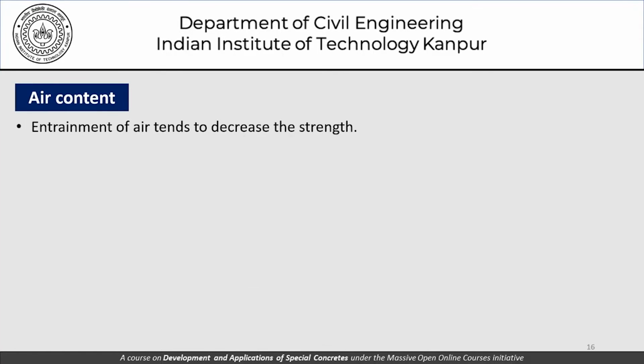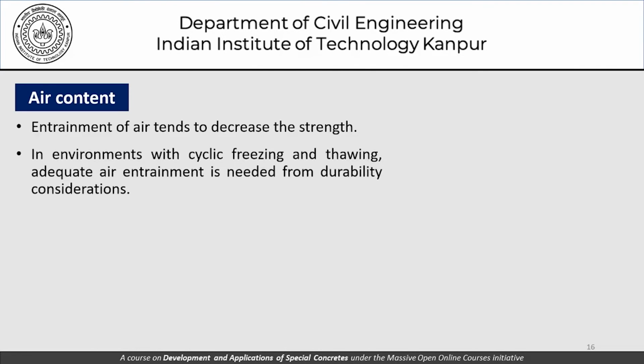As far as air content in high strength concrete is concerned, we should remember that entrainment of air tends to decrease the strength of concrete. In environments with cyclic freezing and thawing, adequate air entrainment is needed from durability considerations, and that doesn't change whether we are using high strength concrete or normal strength concrete.